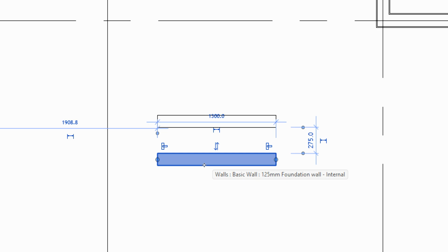But the next question I should ask myself is, for the plaster that I want to assign to it, what should be the thickness of the plaster? You understand? So what thickness should we give for the plastering? Somebody should bring a value. 12.5. Foundation plastering of 12.5 is not advisable, it's too thin, because it's going to go into the soil.